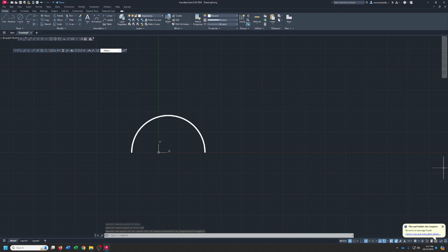Now, when we're looking at the drawing, we've got 300 total between centers. So that means from the center line, it'd be 300 over to the center of the arcs and the circles from the top view. But our top view shows us that the radius of our two sides is going to be 60. So it's going to be 150, which is half of 300, plus 60. So 150 plus 60 is 210. So we'll go 210.